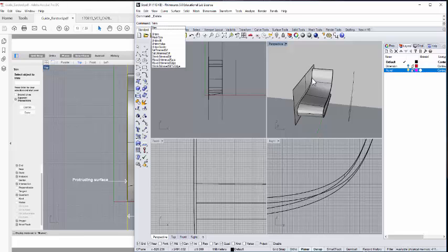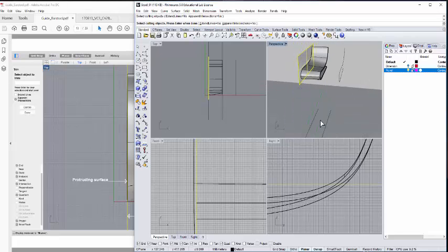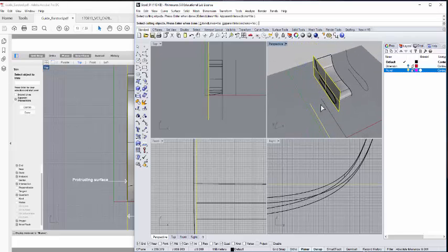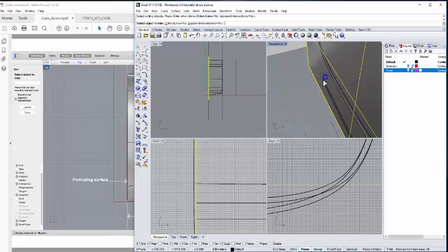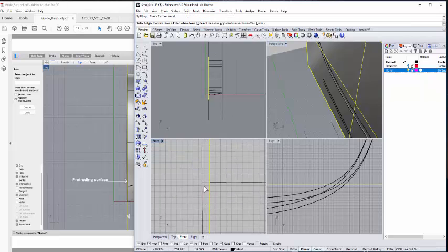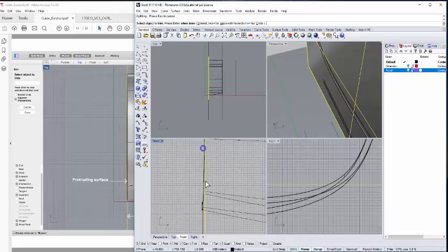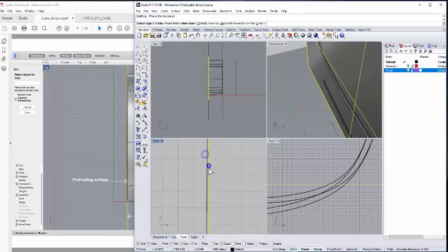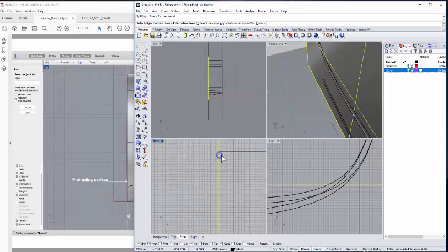Let me just use a trim. So my cutting object will be this. Let me just pick both. Okay. So that's my cutting object. Let me just delete this guy. Okay, let's say for example if you are having the same issue, right? The tendency is always there is a certain line somewhere which is giving you the issues. Let me just zoom in.